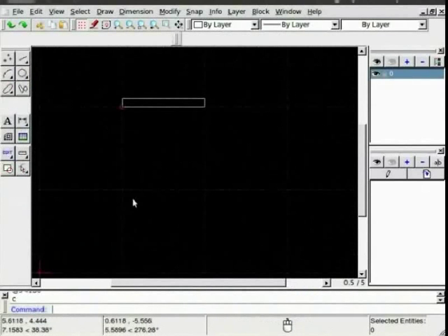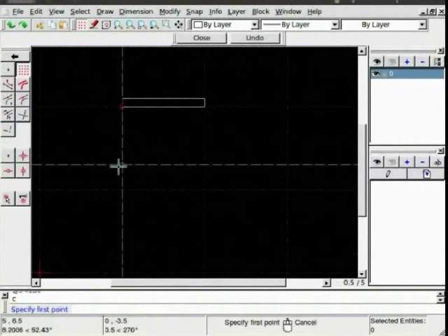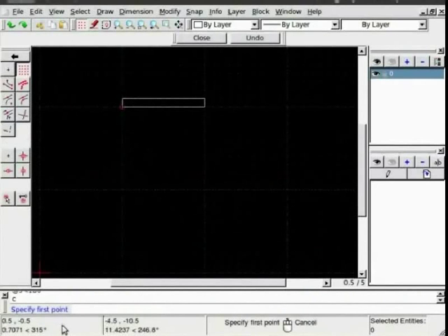Increase the drawing using the mouse wheel. Now I need to draw a trapezoidal portion which is at the 45-degree angle. I'll first draw it below this and then move it back. So draw a point slightly below the original one. So 5, 5. Next point will be at, now this side is a little shorter than 5, so I'm taking 4, angle 0. Then the trapezoidal, or the angular part, which is at 0.53.